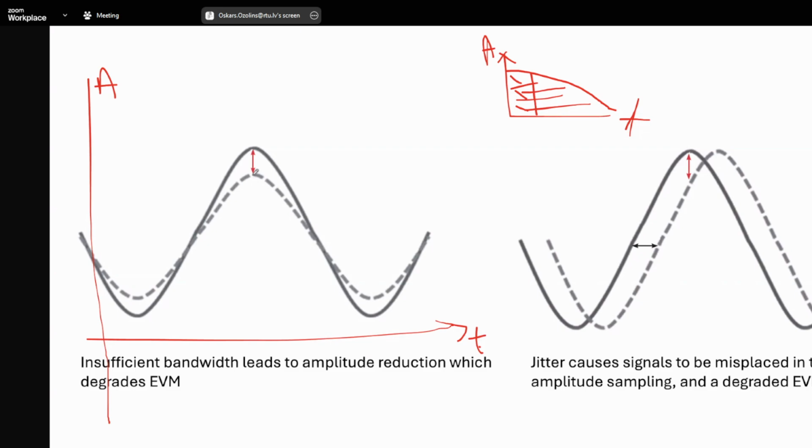This also can be degraded if the channel response has ripple like this, then you have an even broader impact, not only noise, but this ripple is just making the constellation point even larger. So right, with an equalizer you try to guess the response and invert it so you get an ideal waveform. Most often it's not possible to get back to ideal. So right.